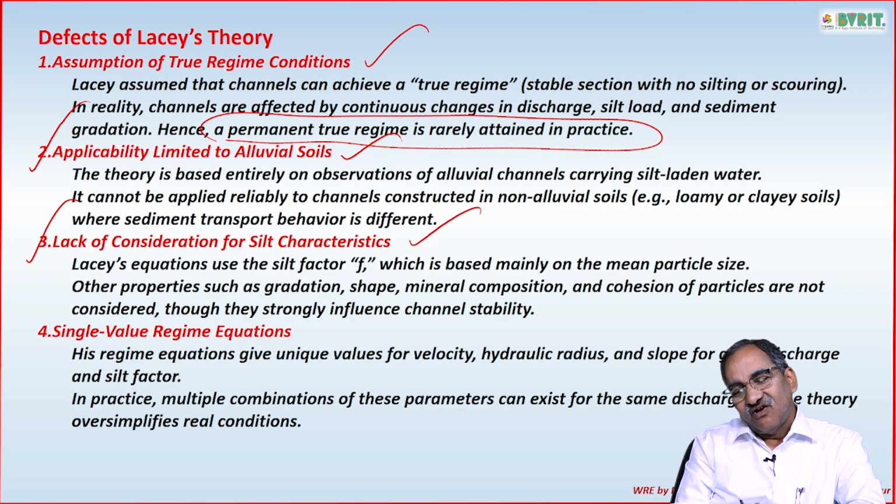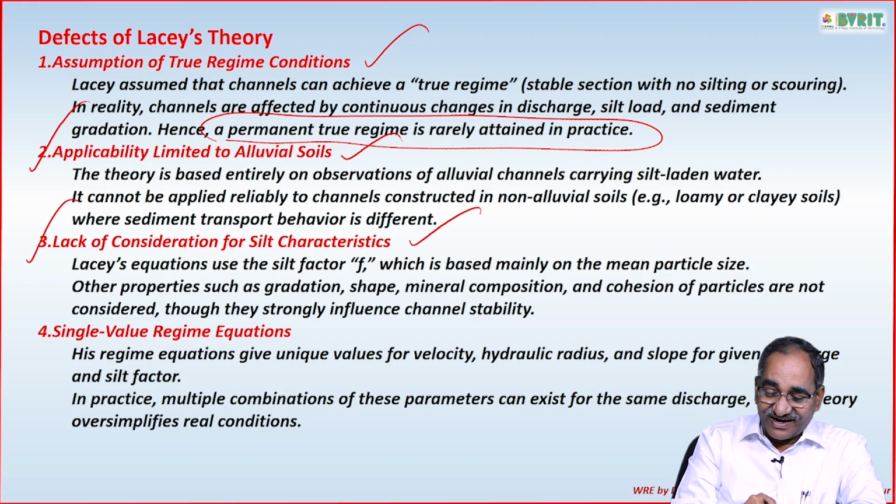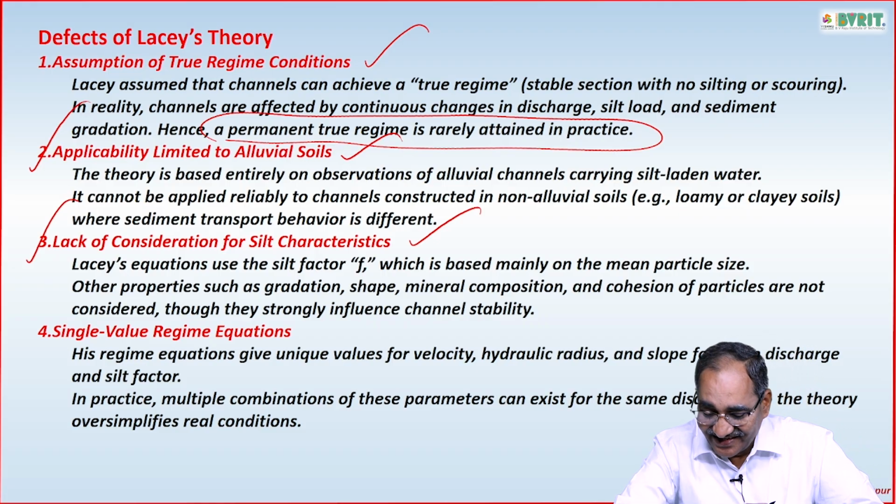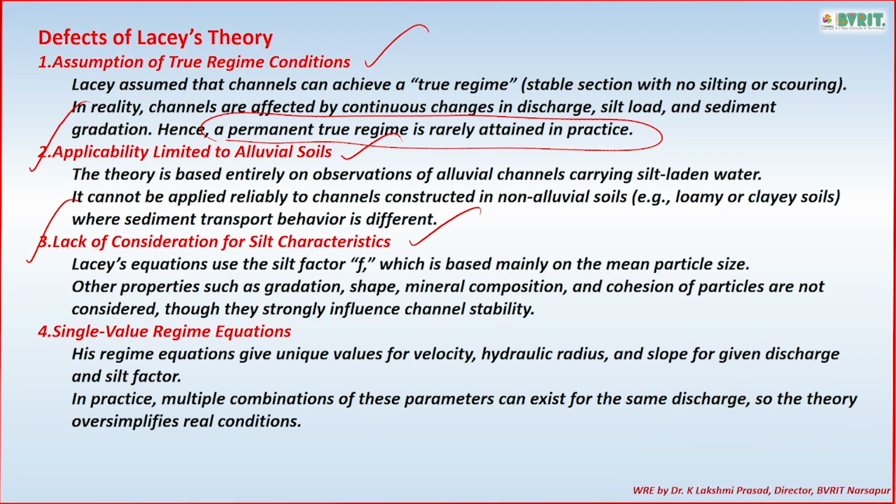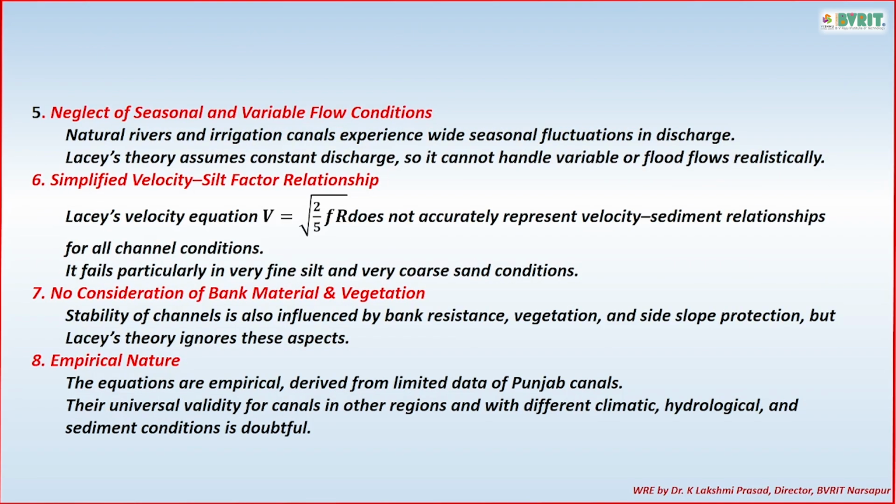So that means all his equations are depending on only 2 things: one is silt factor and the other one is the discharge actually. Generally the entire things are revolving around this. But in practice, multiple combinations of these parameters can exist for the same discharge. So the theory oversimplifies the real conditions.